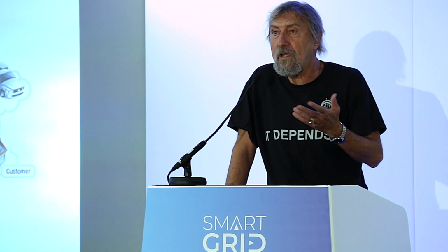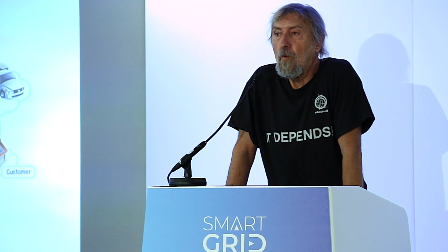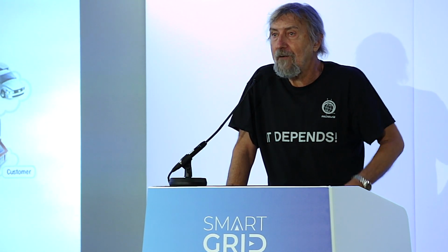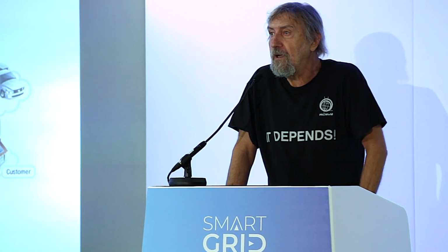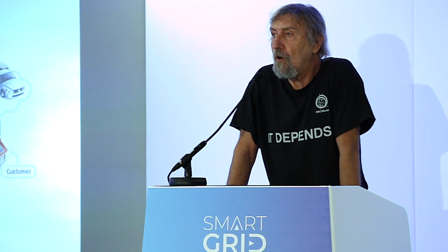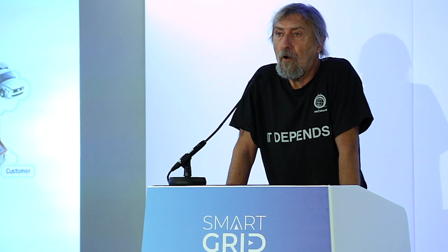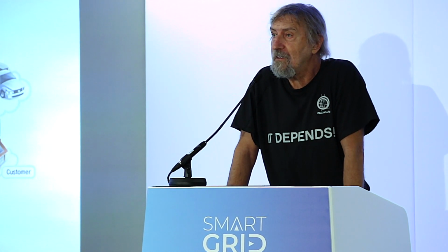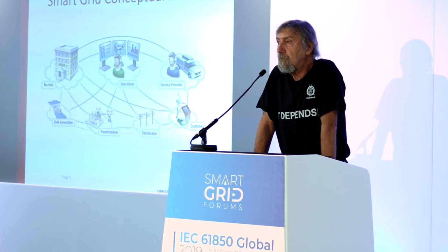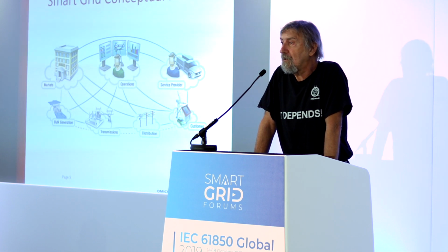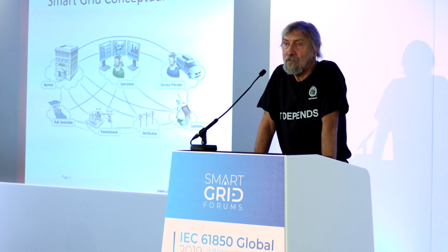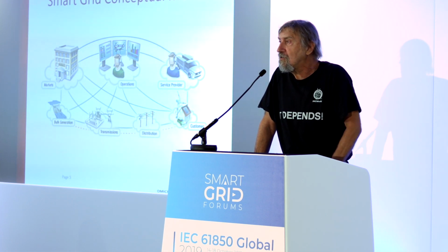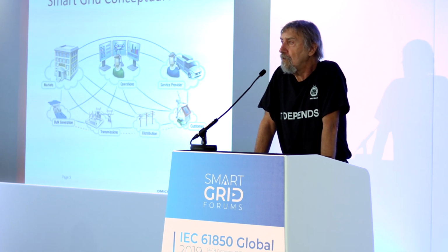If you have wind generation and you have a big wind farm that is covering a vast area, the speed of the wind is not going to be the same. Maybe not all the wind turbines will be operating at every moment in time. So it is a variable characteristic of the generation. And from the point of view of the control of the electric power grid, when you have to deal with variable generation, things become quite challenging. You cannot just do it based on some assumed schedule from the day before based on the load forecasting.